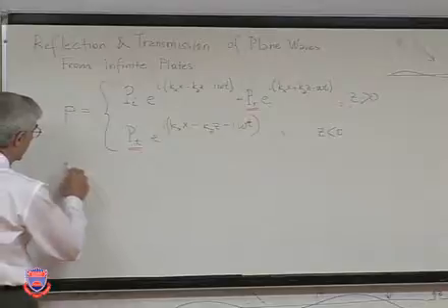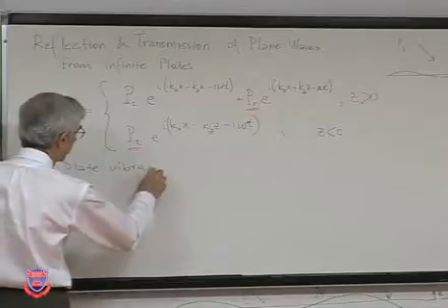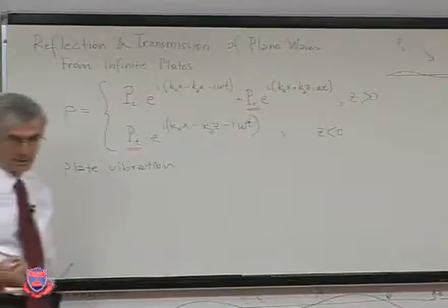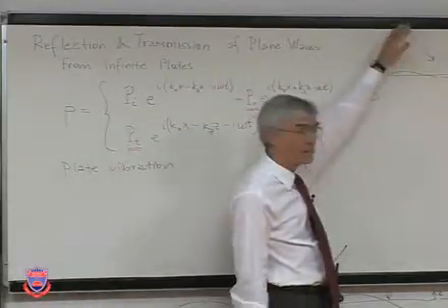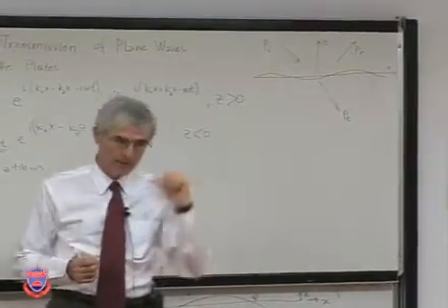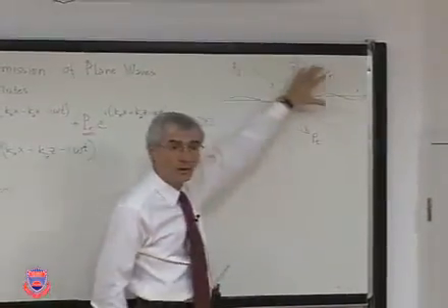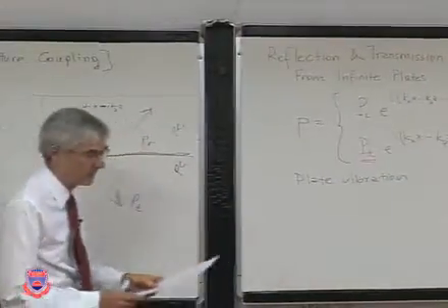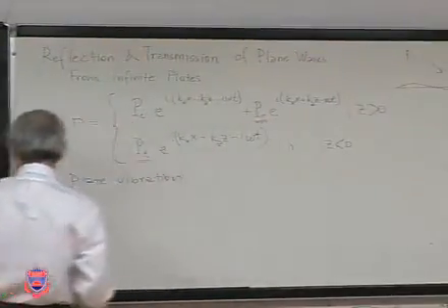But we said that the plate now is plate vibration. And look, we said plate vibration we know, but we do not know in this case, right? Because you have to find the plate vibration. The only thing we know here is sound is coming, okay? We know the relationship between pressure, so we have to find out what that is. And that plate vibration will be a result of all of this acoustic field, because we don't know what that is yet. And that's really what we're trying to find, along with the amplitudes of transmitted and reflected waves.